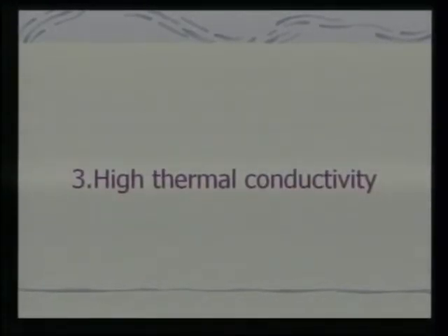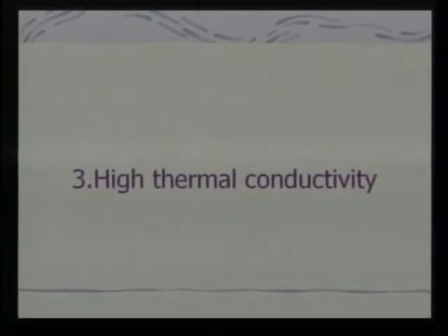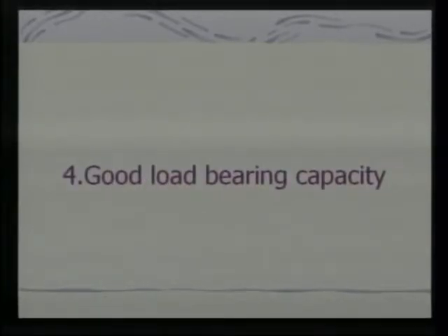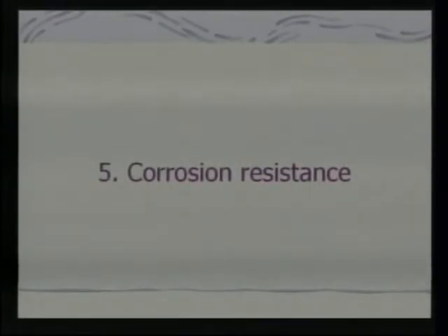High thermal conductivity, due to which the bearing easily conducts the heat generated. Good load bearing capacity. Naturally, the bearing requires this because it is a load bearing element. Corrosion resistance. Usually bearings are subjected to lubrication with various lubricants which may corrode in fact, so it should have corrosion resistance.